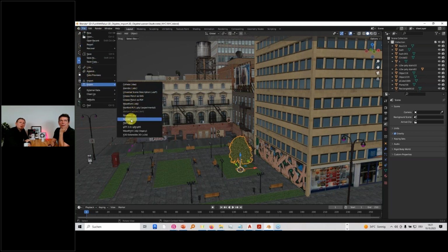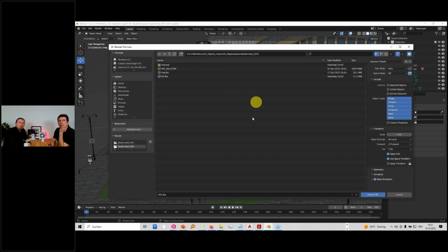And here it's possible in Blender out of the box to store and export this tree as an FBX, OBJ, or Collada. Here you will also have a lot of possibilities. For example, the problem I told you before, in which coordinate system this object will be created. Here you already have in the export the possibility to switch this to a CAD-useful coordinate system where the set coordinate axis is going up. You also have the possibility to use the correct scaling for the export and much more.